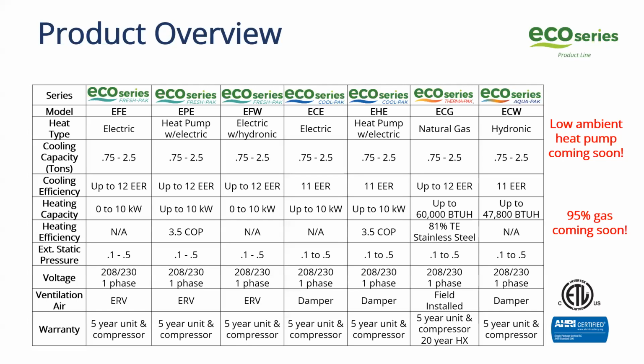And then PTAC, P as in Paul, TAC, that's the horizontal version that you see in hotels and maybe assisted living or nursing homes, where it's under the window. And, you know, it's a small horizontal laid out air conditioner. So it's the same concept, it's packaged, right? It's the heat pump or the air conditioner and the supply blower all in one, but it's through the wall in a horizontal configuration, typically under the window.